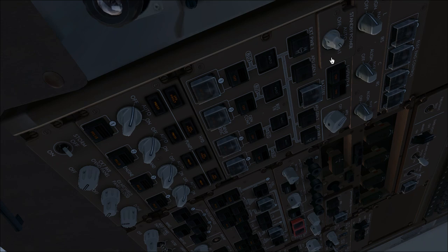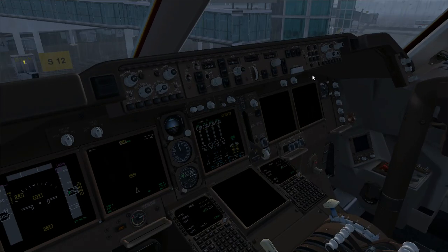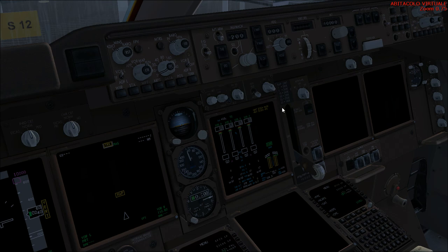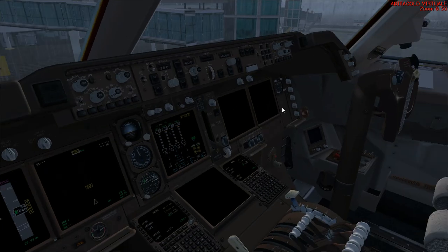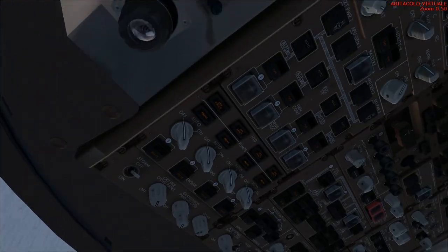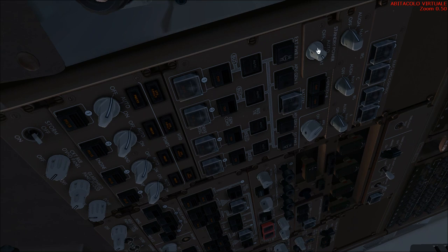So we can set the batteries. In this case, the battery is giving us power for powering the AC system. As you can see in the upper DU, we have battery discharge main and battery discharging APU. This means the two batteries are discharging because we are actually powering the AC system by the inverters, so we can get back to standby power auto, and we have finished the standby power test and also the entire testing for the electrical power up checklist. We have finished the electrical power up checklist.